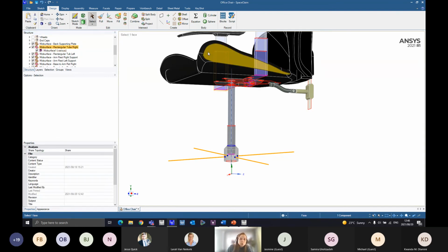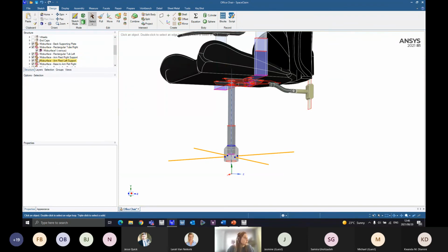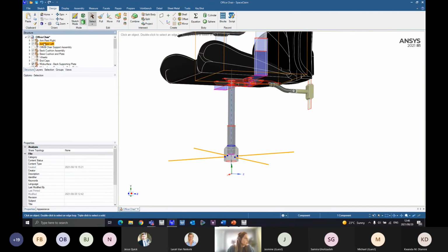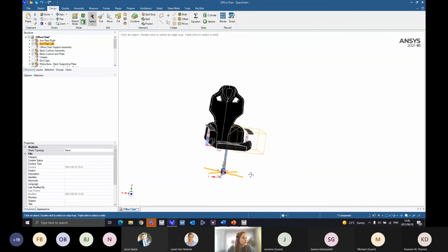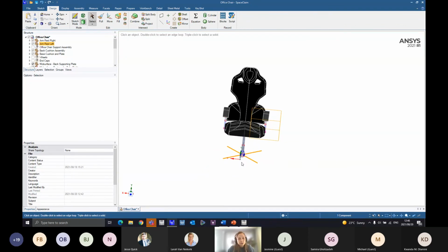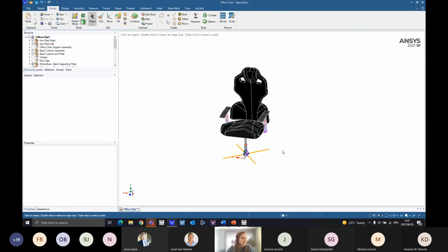So when you import into Workbench, which I'll show you now quickly as well, just ensure that this property over here is actually the share option. There are also other options like none and group. Sometimes it kind of resets to the default, so I always double check that.